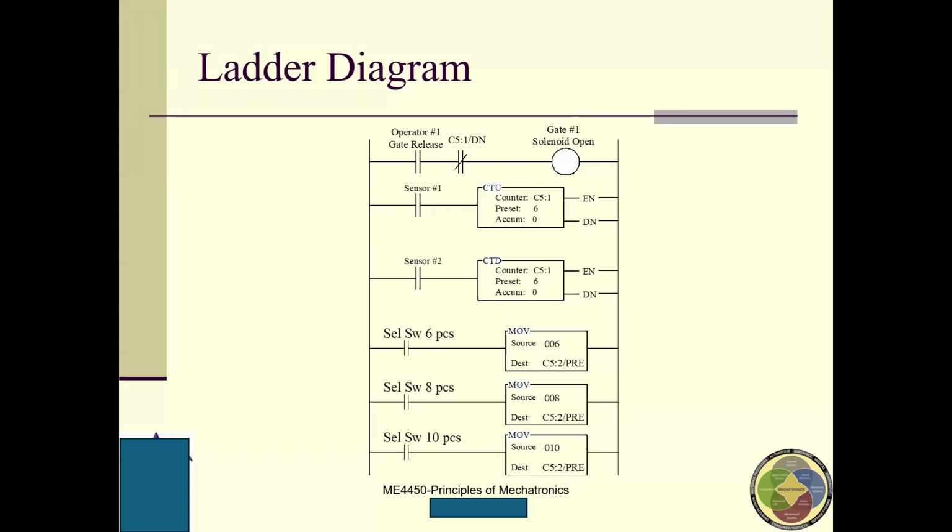So we have the first rung here. It initially can't go through until this is activated. And when you activate this, it can go all the way through, which opens the solenoid, which causes the conveyor belt to move. And then sensor one, when this becomes activated, say something like a block on the conveyor belt goes past, it'll activate this, so this will be energized.